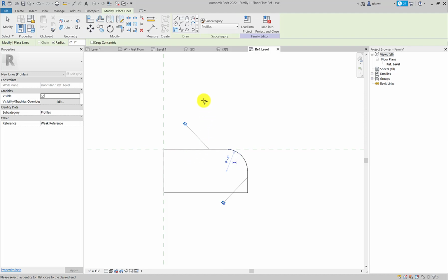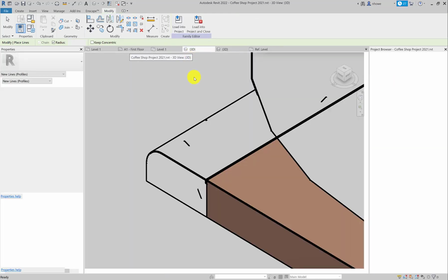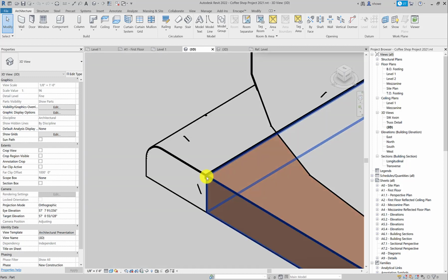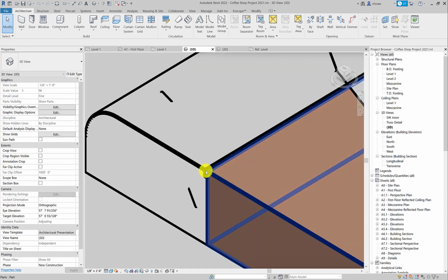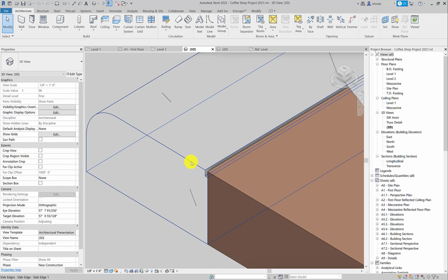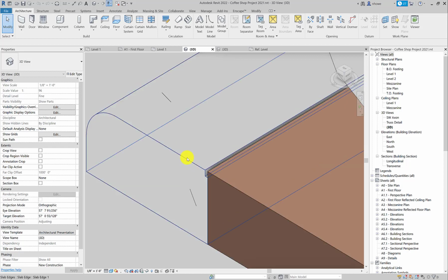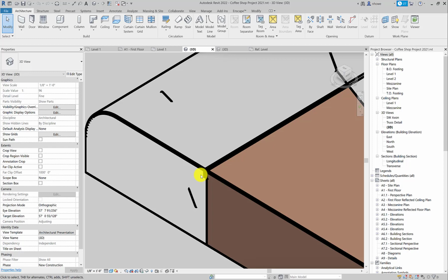One might notice it got really detailed here. If you can't see, it's kind of muddy, so what I'm going to hit is TL, which is thin lines. That allows you to not see the line weight, so you can really look in to see what exactly you've drawn. So TL, remember that's thin lines. And when you hit TL again, it just goes back.